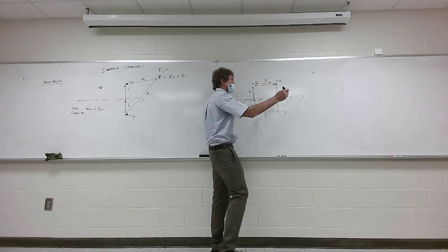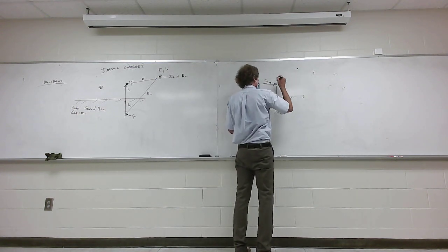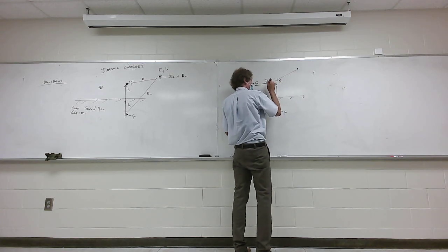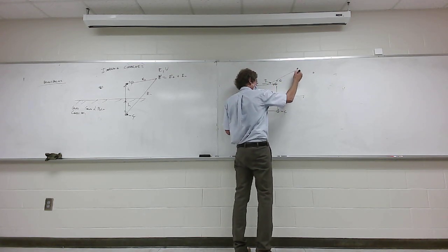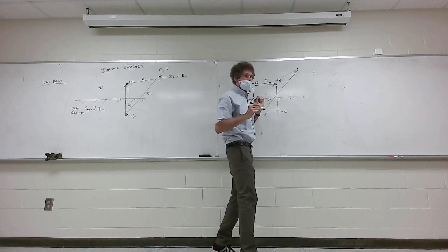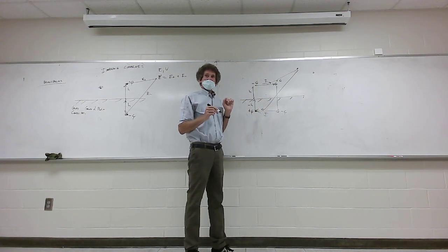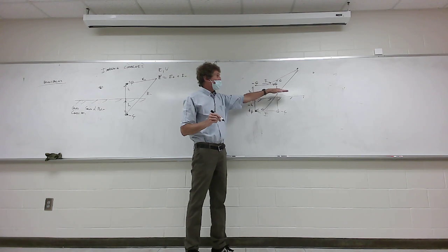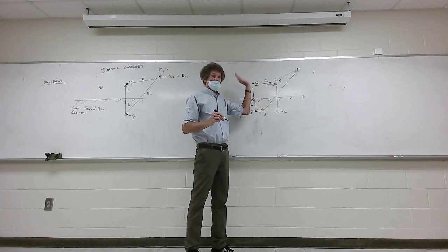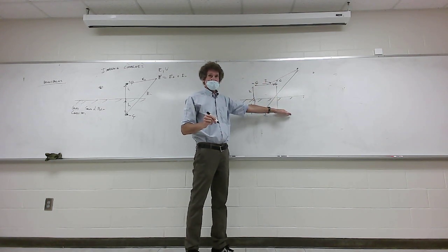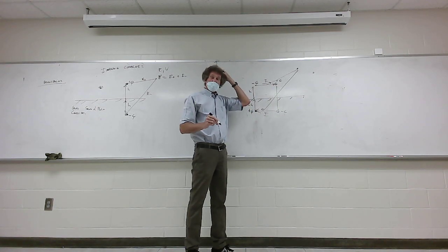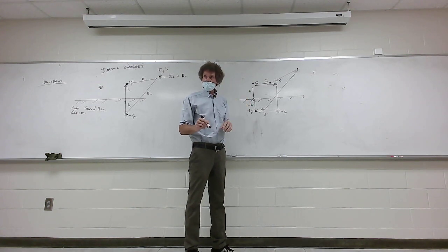Now if you wanted to know the total electric field out here somewhere, you would find the electric field from this short little dipole or from this antenna system and add to it the electric field from here. A point I should make is these fields only exist above the ground plane. They do not exist below the ground plane. Y'all with me on that, class? This is only as a method to get the solution above the ground plane, but nevertheless, it is a solution. Y'all follow me?